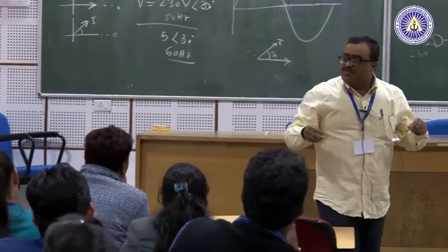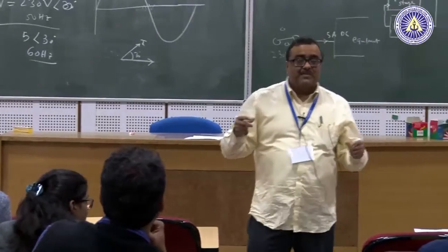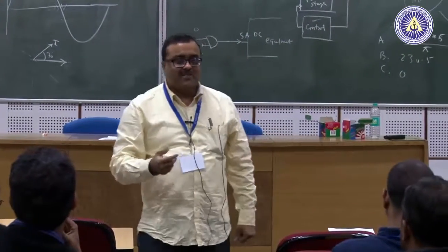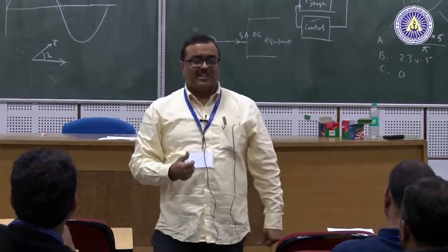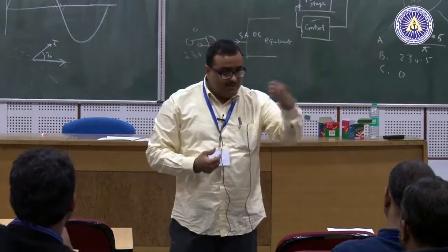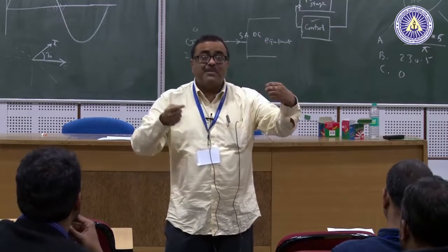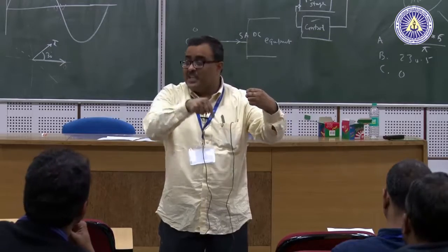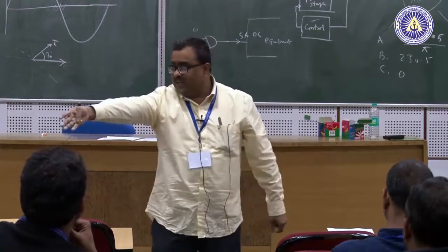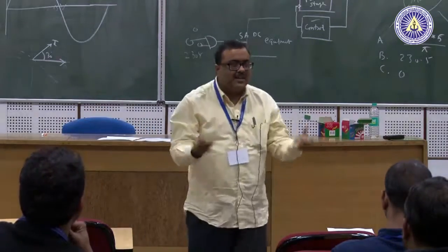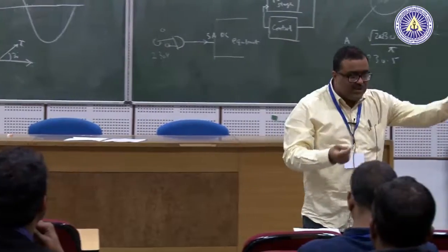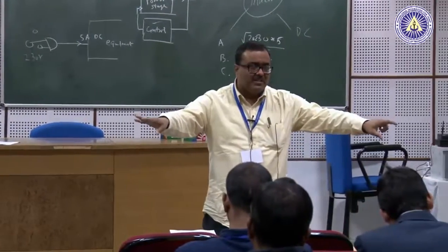That is something we see in power electronics all the time. That is why we have a different definition of power factor. The normal definition of power factor does not work. Why? Because my 230 volt voltage should have some 50 hertz component in it, otherwise the average is 0. What is the fundamental definition of power? Power is voltage times current, averaged out.